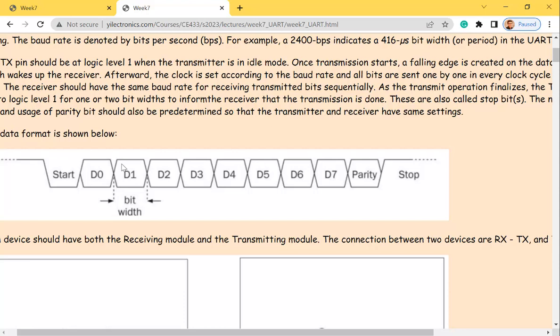Think about that. You have a transmitter and receiver. It keeps sending 1s and 0s from one side, and the other side tries to receive it. If you don't have the same baud rate, this guy is sending 9600 bits per second, and this guy is assuming you are sending 100,000 bits per second. So it's going to sample at different spots. You know what I mean?